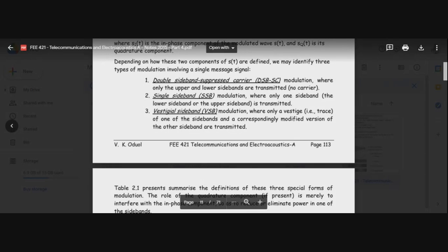It turns on at the carrier, and is up on one side and 0 on the other side to select one of the sidebands. The problem is that a filter like that, with a sharp cutoff, is impossible to design in practice. You can approximate it, but you cannot design it.